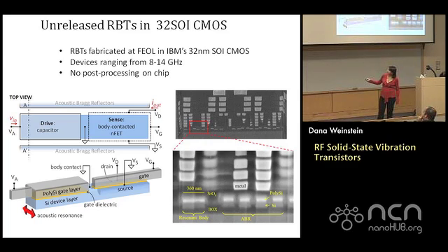So what you see here is a drive capacitor for launching acoustic waves in this silicon bar. This thing is surrounded by oxide. This is shallow trench isolation, defining the silicon islands. And the structure is formed from polysilicon gate and silicon device layer with the gate dielectric sandwiched inside of it. So we can launch acoustic vibrations with this capacitor, and once these vibrations are established at resonance, you can detect them using a transistor on the same island. And that's, remember, piezo-resistive sensing of these vibrations.